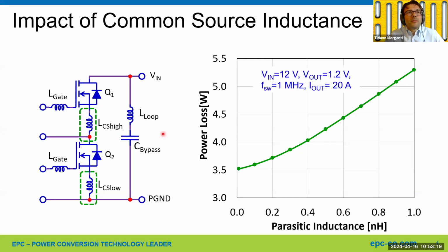And the point is, you need to have not a TO220, but a TO220 by 2 half bridge. So you need to have a single PCB with the half bridge on it. On that PCB, you need to place the small bypass capacitors, so few tens of nanofarad.